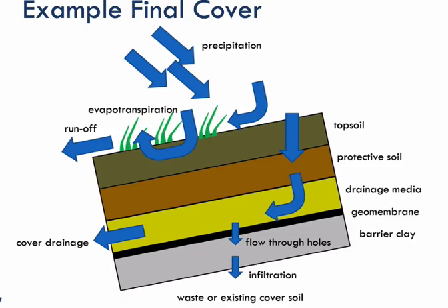And there is, in fact, a large line of inquiry in the low-level radioactive waste management community that looks just at that problem, trying to model the system all the way from where water enters the system to where there are potential exposures. That is not the basis for the design that we are doing. The design that we did is somewhere in between fully prescriptive, which is more typical for landfill final cover designs, and fully performance-based, which is still in its infancy.